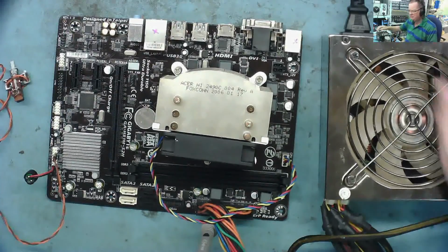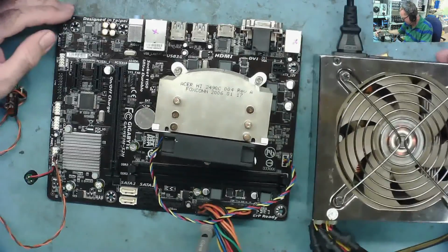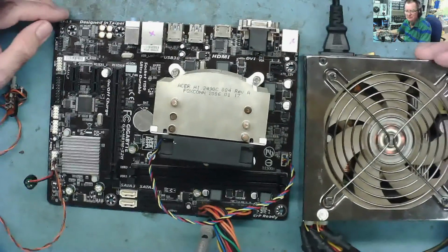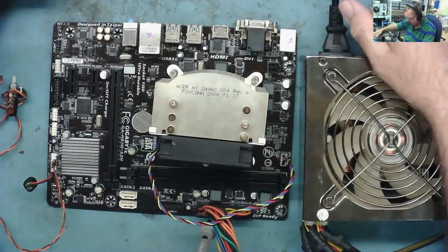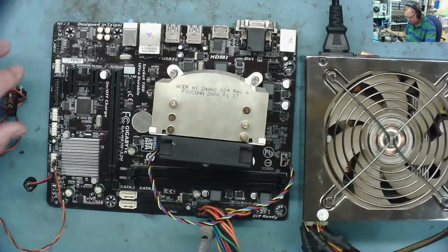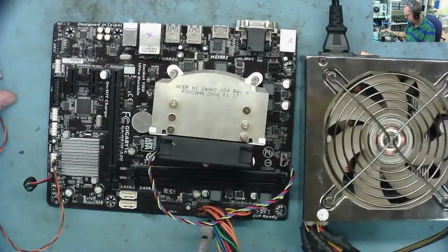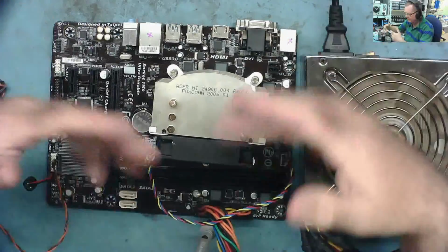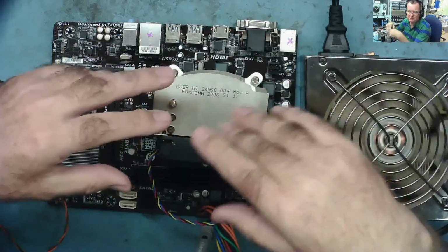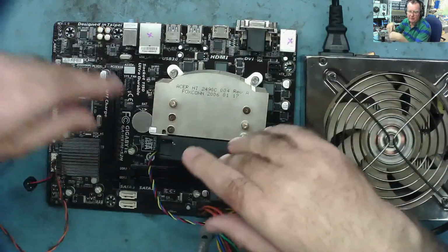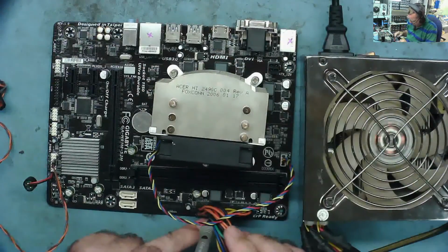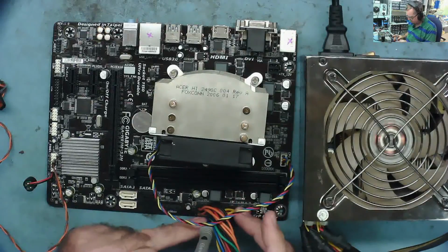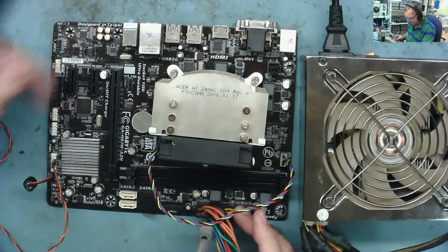Oh, that's strange. Effectively the power supply is tripping out, but there's no shorts. Okay, I've taken my wire back off again. This power supply is tripping out, and then obviously all the power goes off, apart from the 5 volt standby which stays on. So this will go high again, and then it gets stuck in this loop.